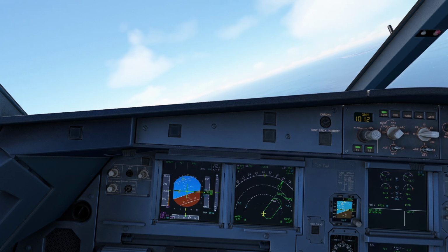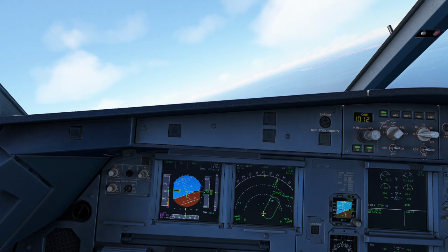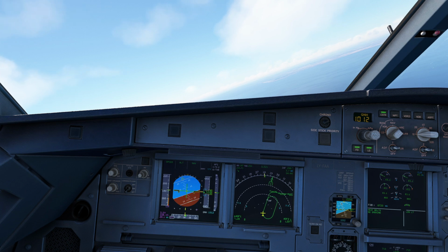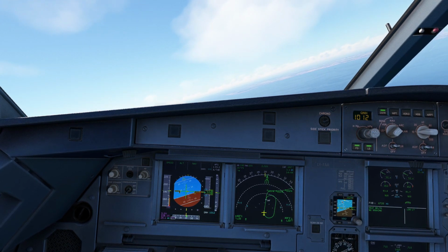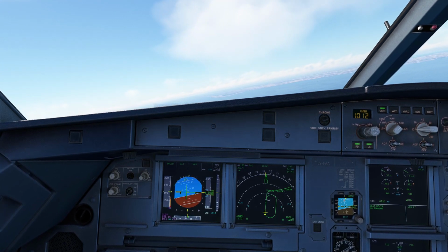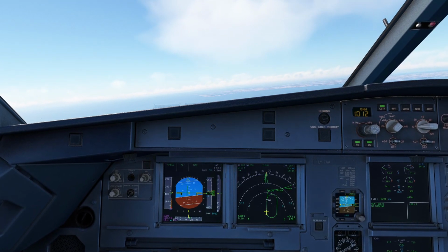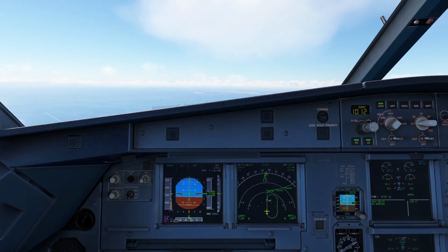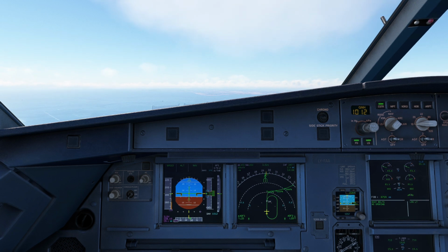But for the in-flight handling, first we will fly the ILS normally using localizer and glide slope until near minima or decision altitude, then expect visual acquisition of the runway before or at the decision altitude, or maybe before, then go visually align with the runway center line during the last segment.